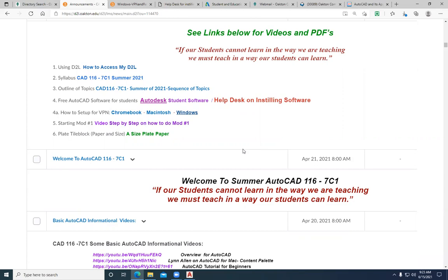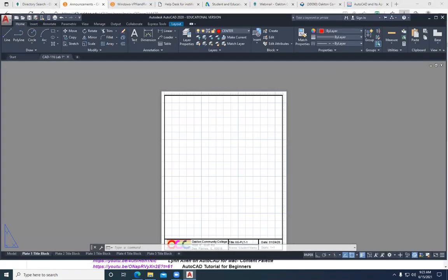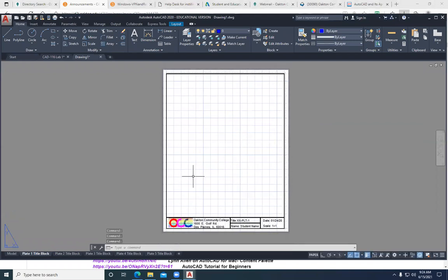So once you have the software installed, if you see a green link like this, if I click on that, I'm going to be able to open that and it'll take you right into CAD. And so here's our CAD assignment. And then the first thing I can do is see if my grid is on by typing grid and then make sure that it's on, and then snap, make sure that that's on. And then as we draw things, we'll go through and show you how to create these different shapes on the computer. That's if you have AutoCAD installed. Correct. You need AutoCAD.